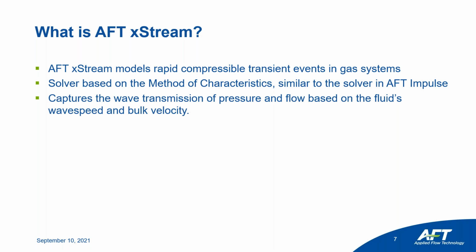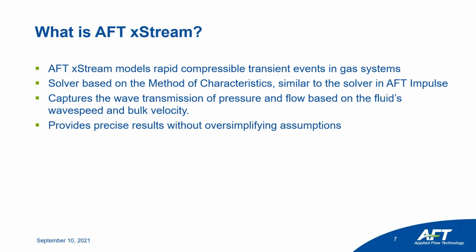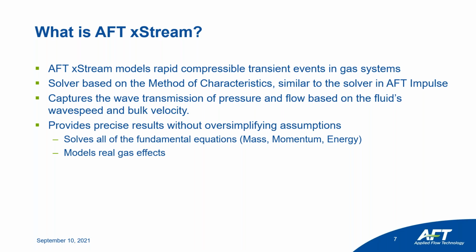So it will capture this wave transmission based on wave speed and bulk velocity. Those things, again, are going to be changing down the length of the pipe, which makes things a little more difficult. xStream provides precise results without oversimplifying assumptions. It will solve all the fundamental equations: mass, energy, and momentum. It models the real gas effect, so it's not just an ideal gas equation of state that we use. There's Redlich-Kwong and some others. There is heat exchange, so it's not just assumed isothermal. We don't make the assumption that things are either isothermal or adiabatic.